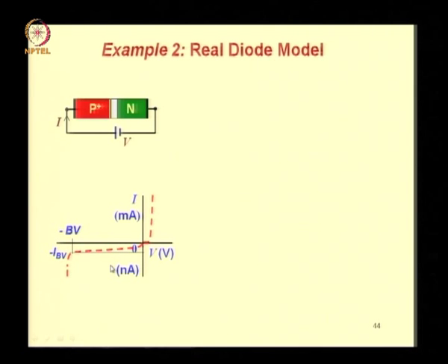We are considering a small signal diode. There are some variations in the shape of the forward characteristics which are not so evident here. We will be including the effects such as generation recombination for small voltages and high injection level and voltage drops across the quasi neutral regions under high voltage conditions.